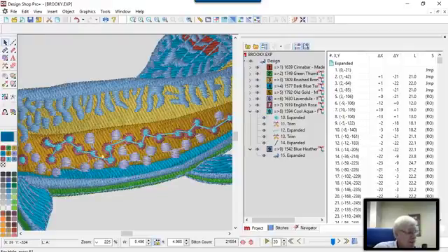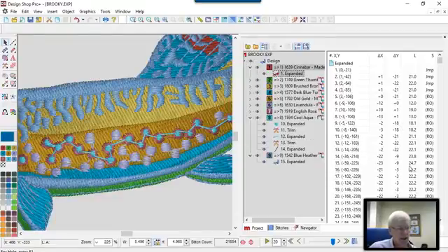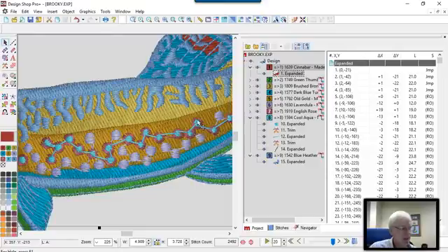Why doesn't it trim the aqua, which really is going to be black, colored dots? Why doesn't it trim between every dot? Well, as we can see when we highlight it, I showed you that there is 1 jump in between each one of these dots. Remember, our jumps to trim setting is at 3. So it's not going to trim because it doesn't meet the threshold. So the answer, what to do there, is to just lower the setting.